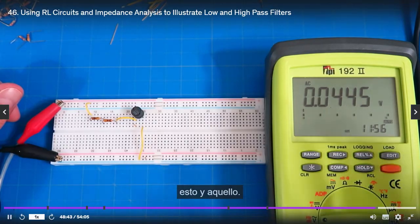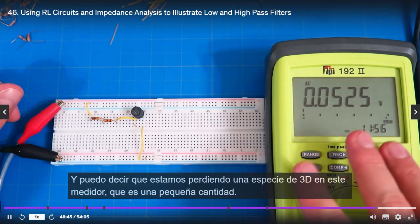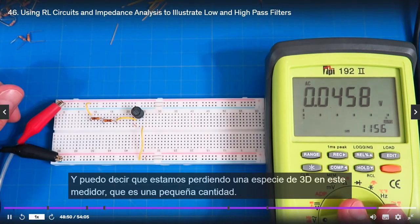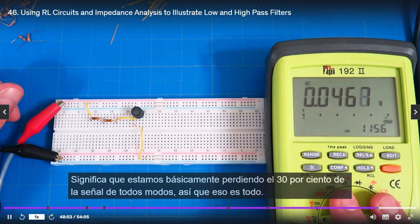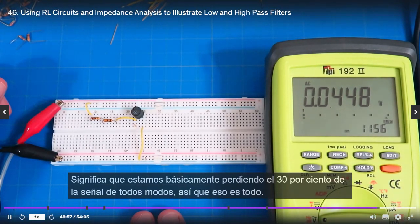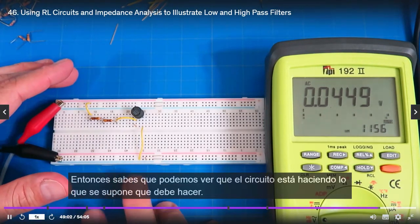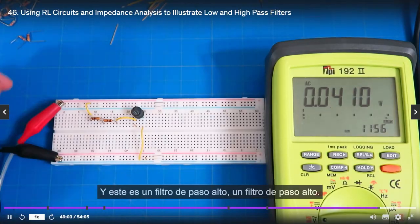So when we talk about filters in the next lecture, we will see what decibels are and gains and this and that, and I can kind of tell that we're losing about 3 dB on this meter, which is a small amount. It means we're basically losing 30% of the signal. Anyway, so that's it. We can see that the circuit is doing what it's supposed to do, and this is a high pass filter, right?